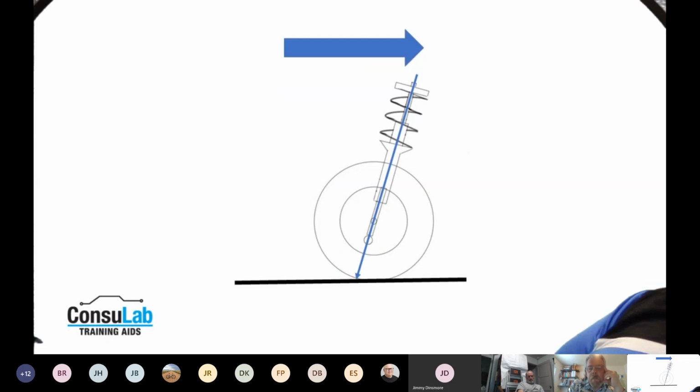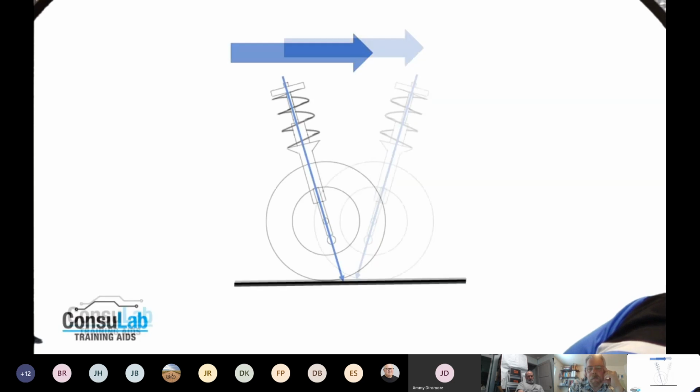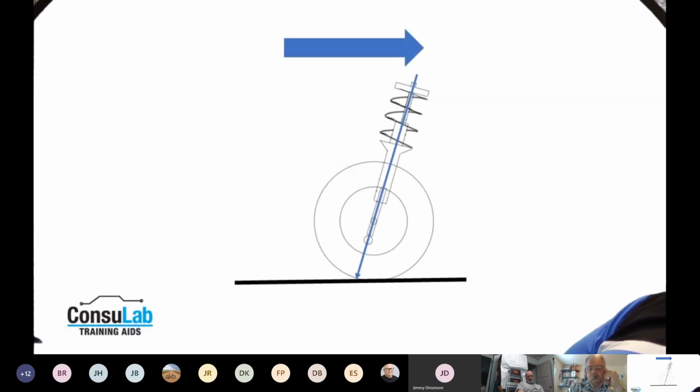If we tilt the axis the other direction, now where the tire is leading the load, that is referred to as negative caster. So in both cases, we're moving from left to right on the screen. Again, lots of exaggeration in these, but it helps to do the explanation. So we go with positive and negative caster.